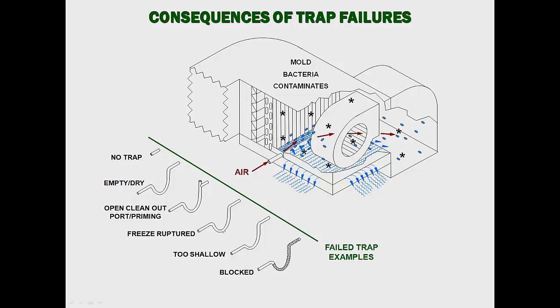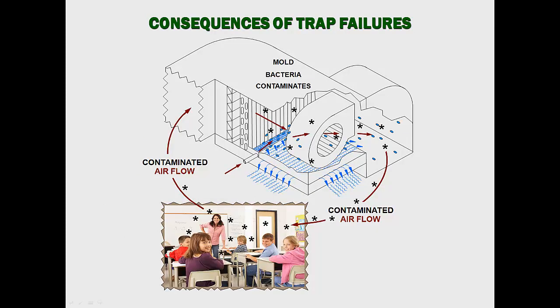The property damage and maintenance effort required for this type system eliminates any hope for low life cycle cost. Further, since all the air inside a building may pass through the contaminated air handler several times per hour, health-threatening conditions are virtually certain. Thus, the use of systems equipped with condensate traps in reality rules out the realization of sustainable green buildings. The photographs that follow show examples of the damage that condensate trap failures cause to equipment and